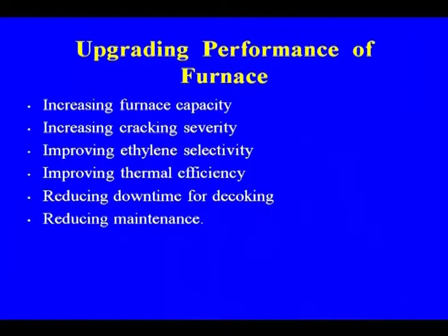Reducing the downtime of decoking is also very important, because normally after a certain run length, when excessive coke formation is there, the furnace is bypassed for the removal of the coke, so that downtime has to be avoided. Reducing maintenance is also one of the important factors which affect the overall running of the furnace.